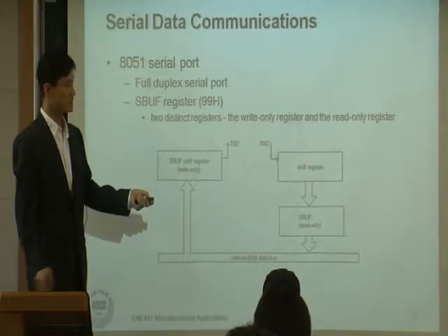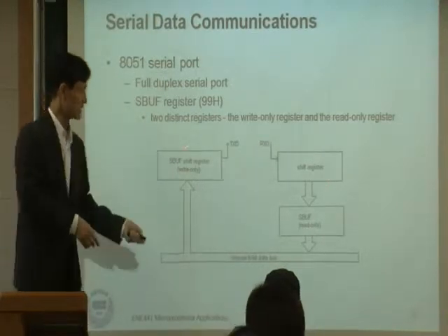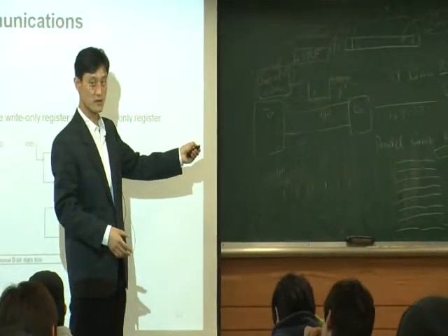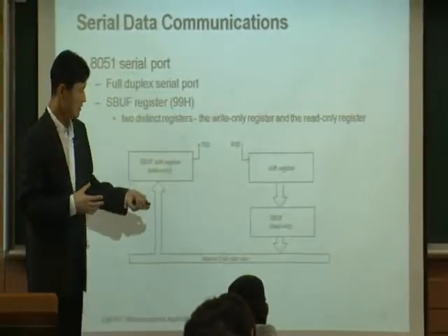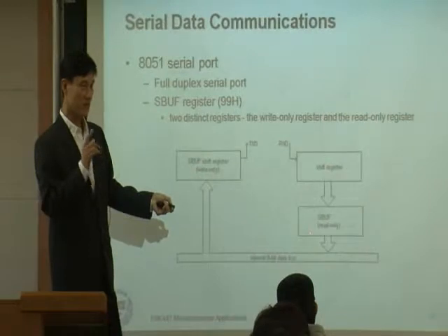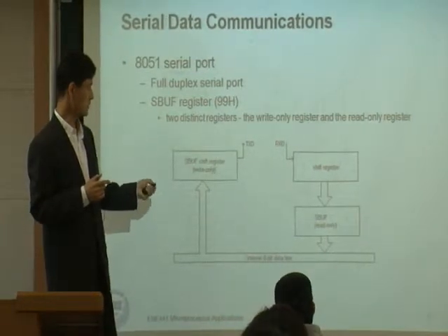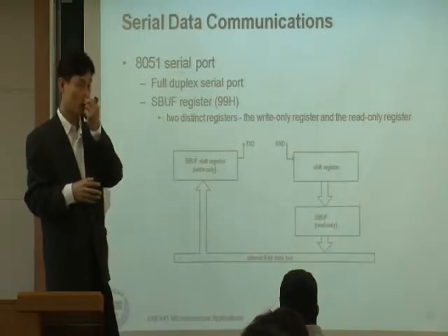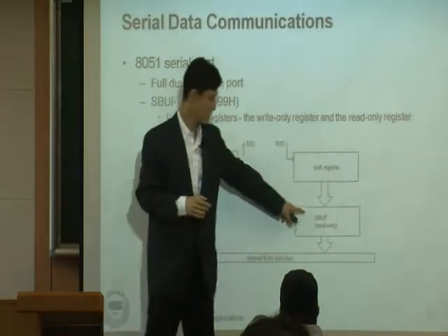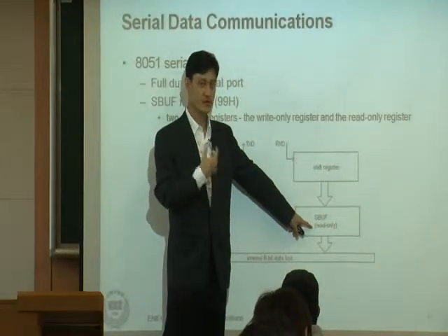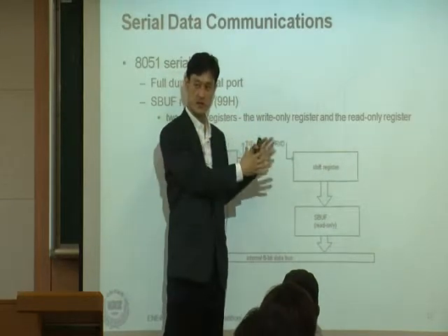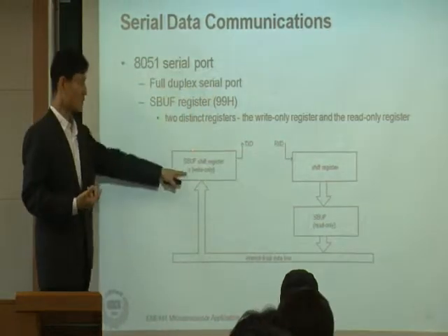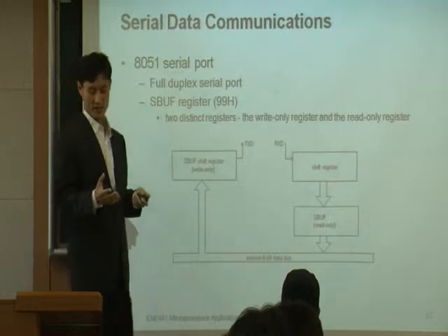This is inside the serial communication hardware. Inside that hardware, we have SBUF, but in fact, there are two of them. One SBUF here, another SBUF here. But this SBUF is read-only for the software, for us, since we are using this processor. Whereas this SBUF is write-only.